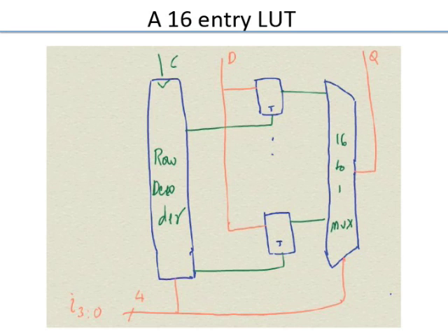The selected one, you always have one word line which is always on, so that latch is transparent. So whatever data is there will come out. If for some reason that data changes, because maybe that wire is connected to something else, then you are in trouble. So that is why it's good to have a very clear notion that when I do a write, there's one cycle where I do a write because I have write enable asserted.